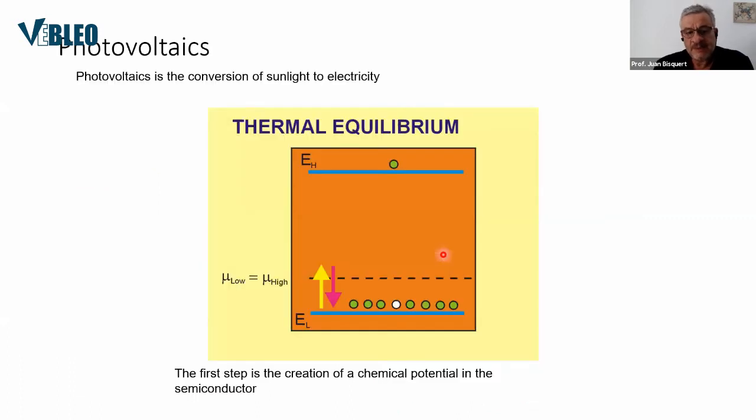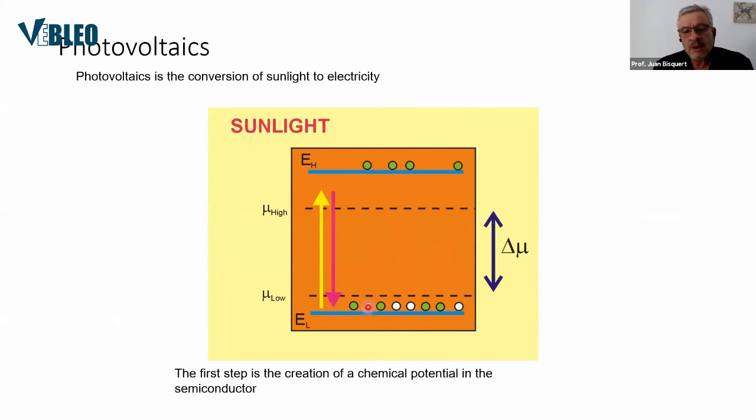This was developed over many years, and the main concept is that when you have a semiconductor, you have carriers in two different states, and they are basically in equilibrium with the surrounding radiation. Then when you produce light, you have an increase of pumping to the high energy state, and then an increase of recombination, which is falling down from the high energy state to the holes here.